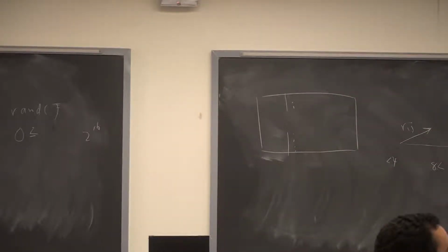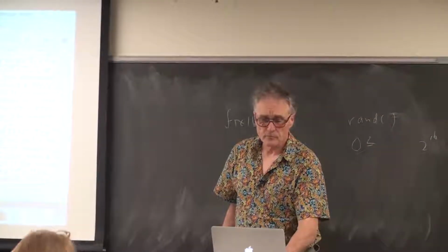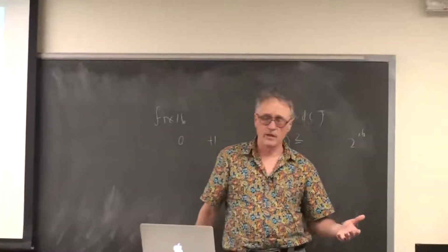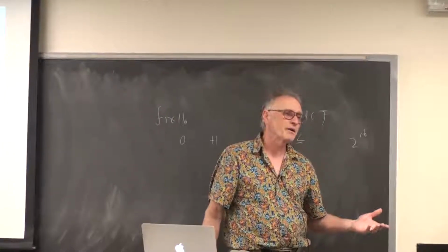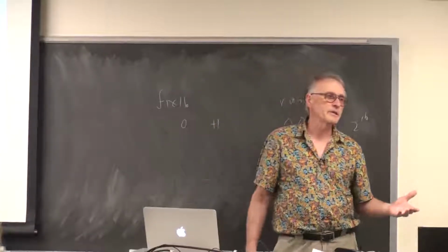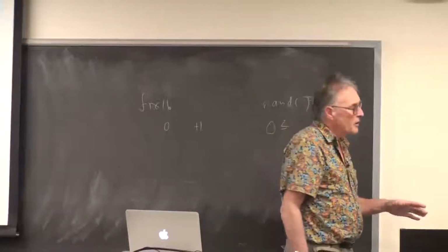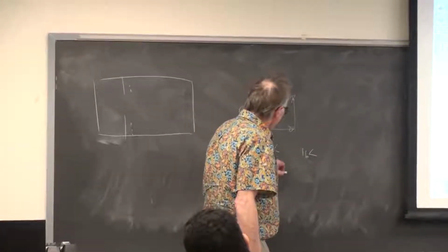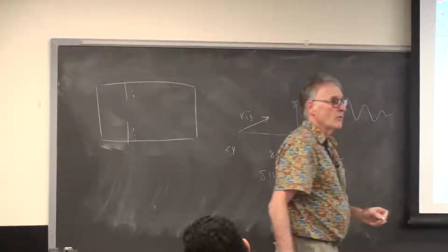How do you generate a sine table in MATLAB? From an audio file. If you have any WAV file, audio file, not an MP3 or anything, but just an uncompressed WAV, then this code will generate 4-bit samples. You'll have to modify it for 12-bit samples, but it's fairly straightforward to do that. But you're going to do a WAV to header conversion. You also, of course, in MATLAB could just compute a damped sine wave. Sine omega t times e to the minus t over tau will give you a nice damped sine wave, which when you play it will go blink.